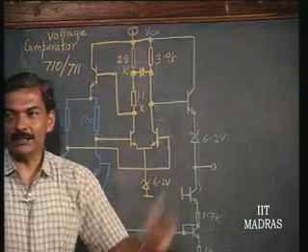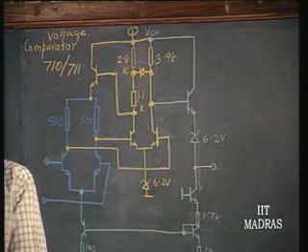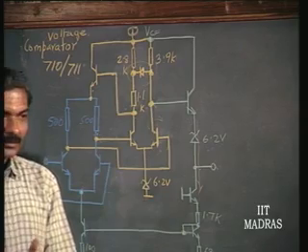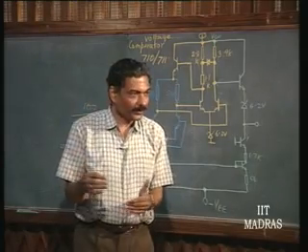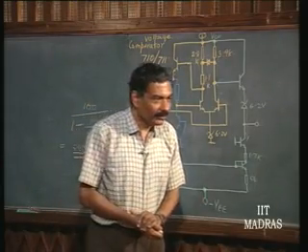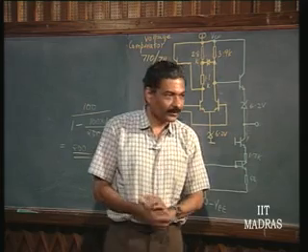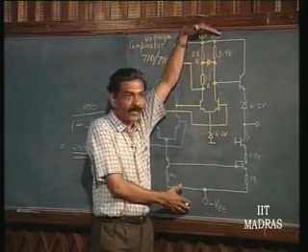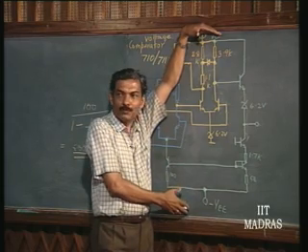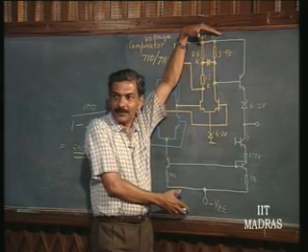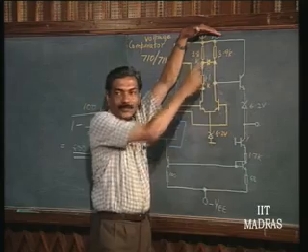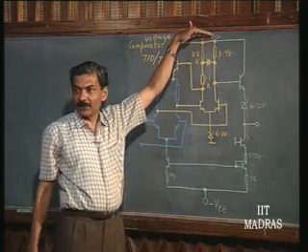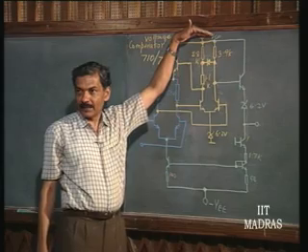So that the output potential is a range within the high range. It should be less than 5 volts, greater than maybe 2.5 volts. So, anywhere between 2.5 to 5 volts. That is, for all the supply voltage ranges, it should lie within this range of 2.5 to 5 volts. Okay. So, this clamping structure is for that purpose. The output level obviously depends upon the supply voltage you are using, what it is exactly.